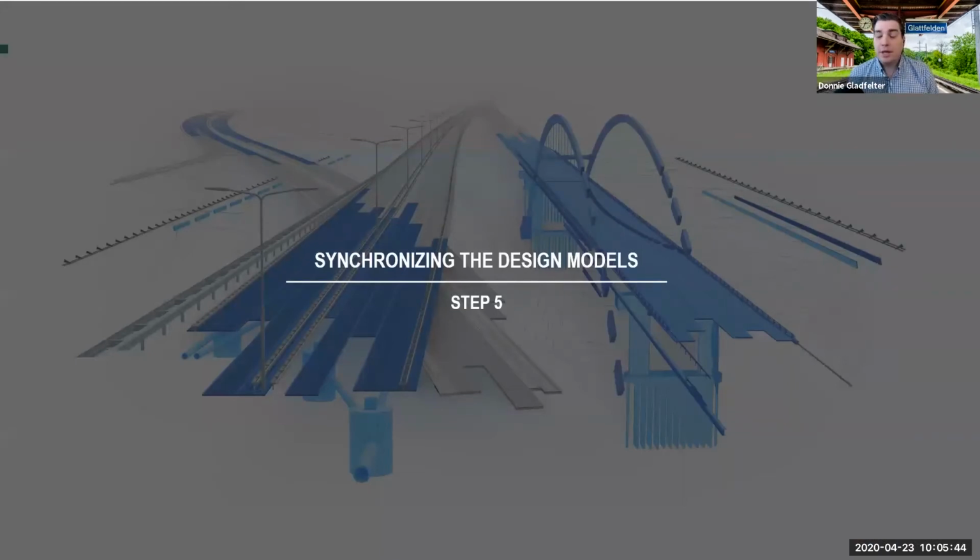This is where I think things start getting really fun and exciting, because we have at this point coordinated Revit and Civil 3D together. And so we've kind of seen how we can export things from Civil 3D and bring those into Revit. Since we've set that shared reference point, we've set the real world coordinates of the Revit model. And likewise, we can export things from Revit and bring those into Civil 3D at real world coordinates. Again, the key piece here is that we created that discipline model of Civil so that we can manage things, and we'll do the exports from the Civil model.